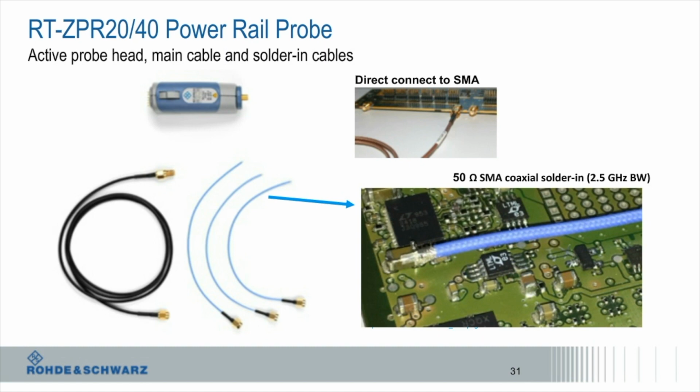I've also seen some development teams, there's a picture of it on the top part, that will just use a straight SMA connector. This requires a development team to think about their board design initially and to have a desire to route out power rails to SMA connectors.